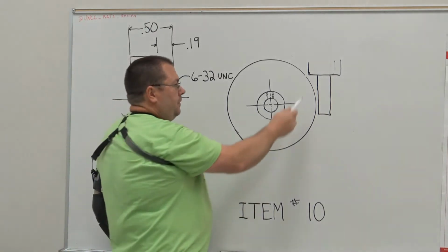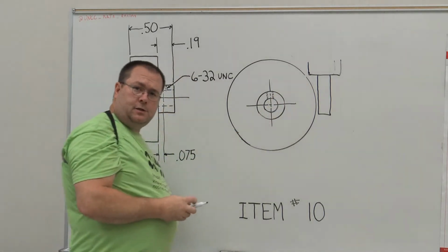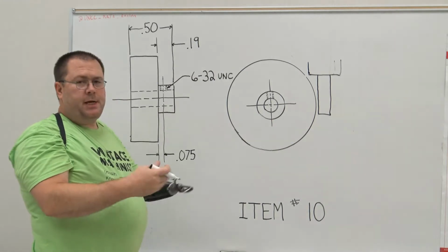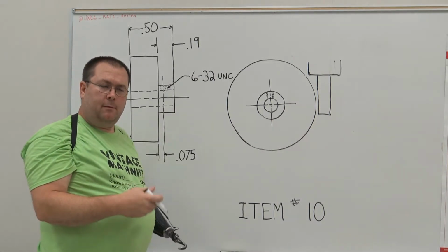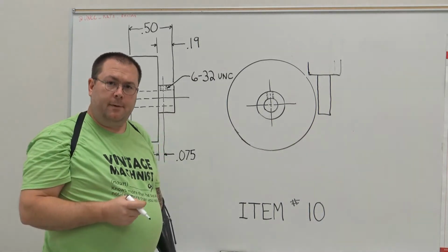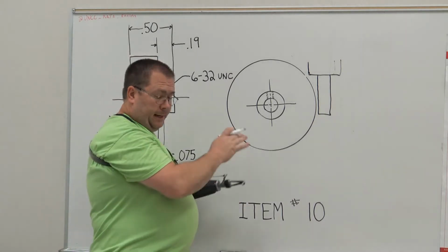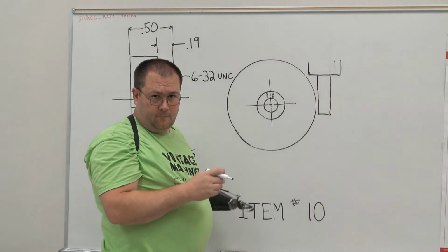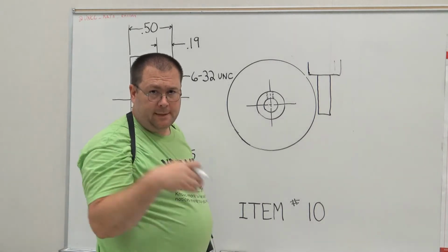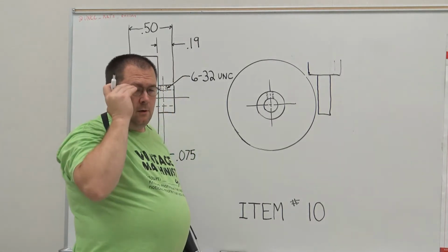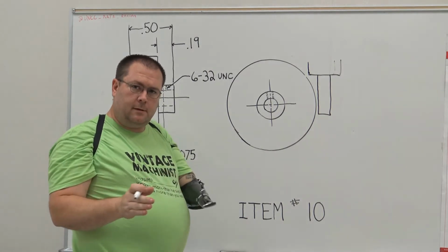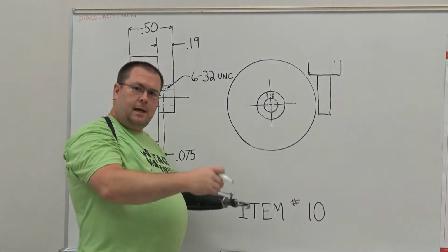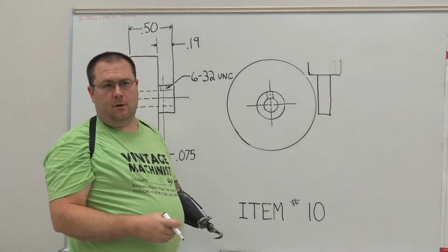Okay? We have to think about how fast we're going to run that edge finder. When we had machines that actually ran faster, I would say 2,000 RPM and above. Well, most machines you're going to run while you're in our program, you're going to max the spindle out, or try to stay in that 2,000 RPM range. Once you get on the mills on the other side of the wall, they'll run to 4,000 RPM.